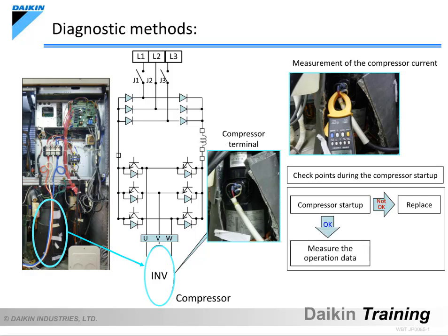If the compressor starts up, measure the operation data and check if there is refrigerant overcharge. If there is, then rectify it.